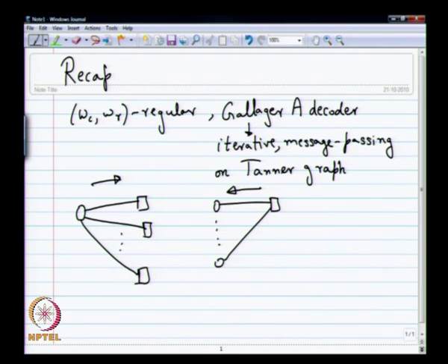And we also saw this idea of density evolution, which is very crucial, which gives you a nice handle on what is actually happening. What is the idea behind density evolution? Tracking the probability that a particular message is going to be in error, that is the main idea. How do you track that? You have to take a lot of care in doing that. The first assumption that is crucial in density evolution is that the all 0 codeword was transmitted. That can be justified by some means.